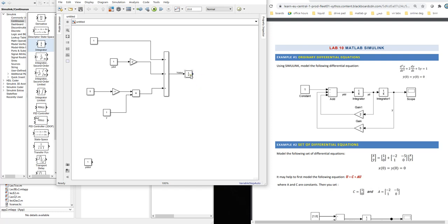If you integrate the y dot again, so Control C for the integrator, Control V again, connect this one to here. Remember that the output from here, double click again, create annotation, the output should be y dot. So integrate the y dot again, it should give you y. So the result comes from here, guys, double click here, same thing, it should be y.